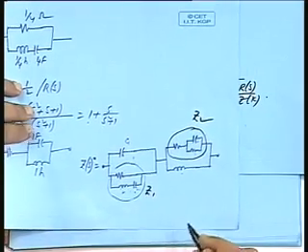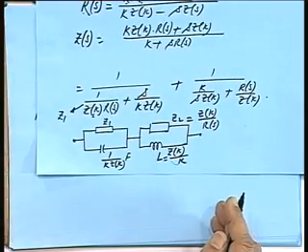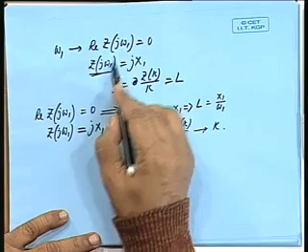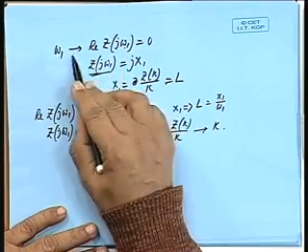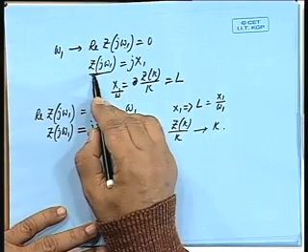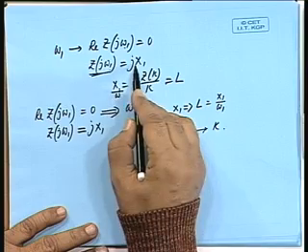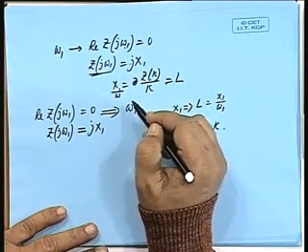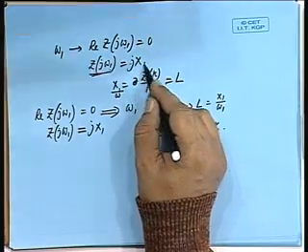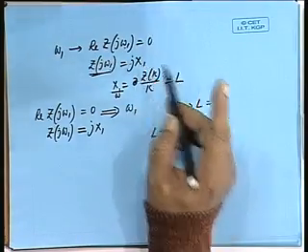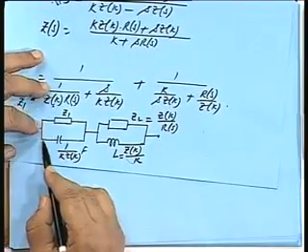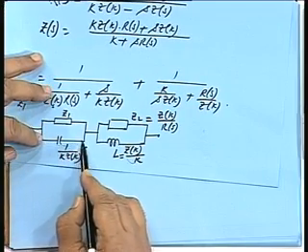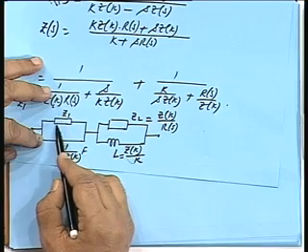If you have, instead of plus jx1, at that particular frequency omega 1 when the real part vanishes, suppose Z is having a minus jx value. It can be plus jx or minus jx. Suppose it is minus jx1, then this is capacitive at that frequency, so you would like to equate it to this capacitive impedance. That means as if the current is made to flow through this, so this is an open circuit.